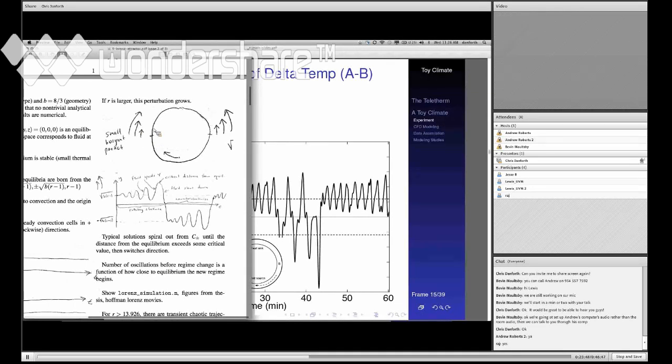It spends less time cooling as it goes through the top half of the loop. And when it gets over to this point, it's even warmer than it should have been last time. And it wants to decelerate the fluid even more, even though the bulk is moving in this direction. And that's why this decelerating arrow is pointing back up. Hot things like to rise. This thing is sinking. It's a hot thing that likes to rise and it's sinking. So it decelerates. Spends less time on the cooling.